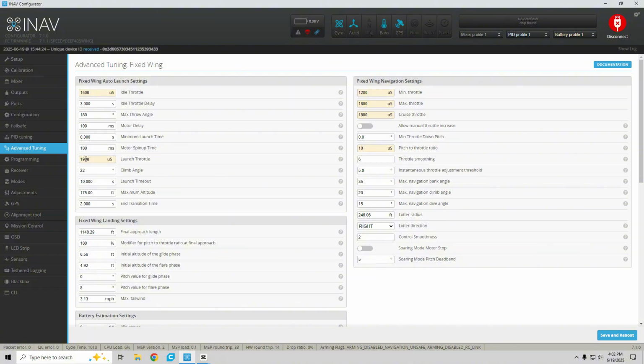The reason why I do 15 and 19, the difference in between, is because if I went with like 13 and then I went with 19, it would give me a lot of torque twist, and you would see the plane twist. I could probably even bump this up to 16 and be like 300 away from 19, but this right here works for me. Like I said, if your plane's faster, you got more power behind the plane, yours might go with like 13 and 17 or 12 and 17. But this is a happy medium for me.